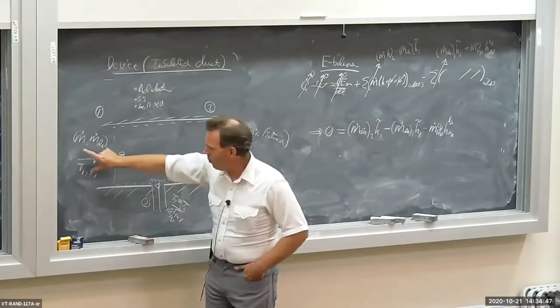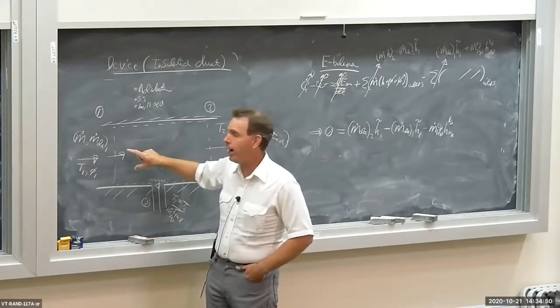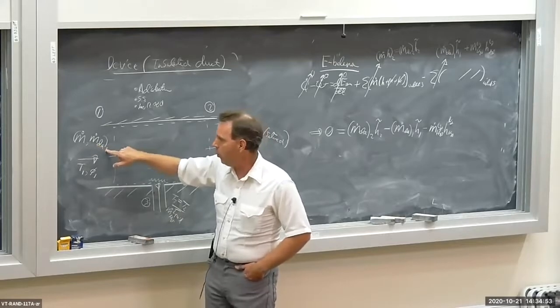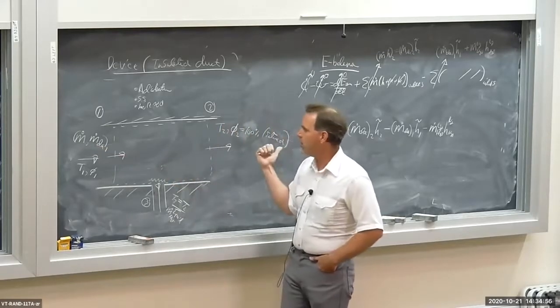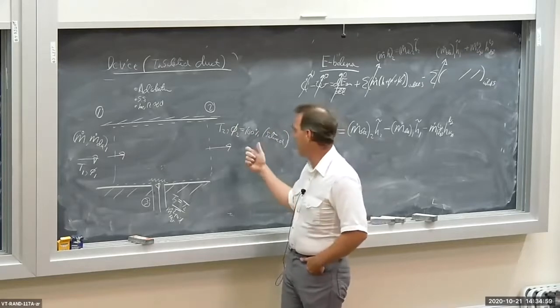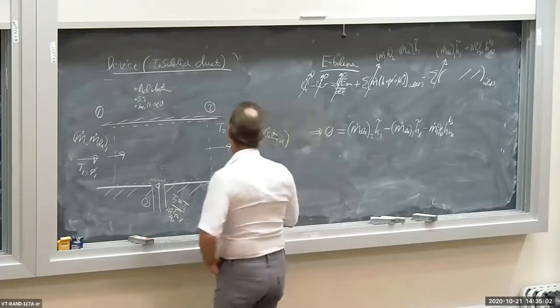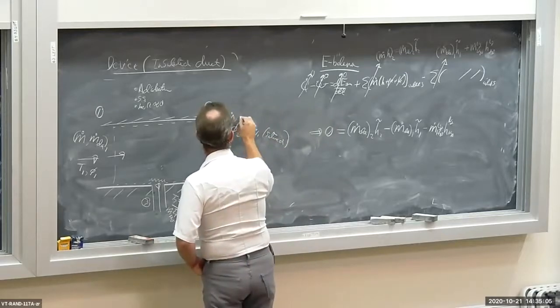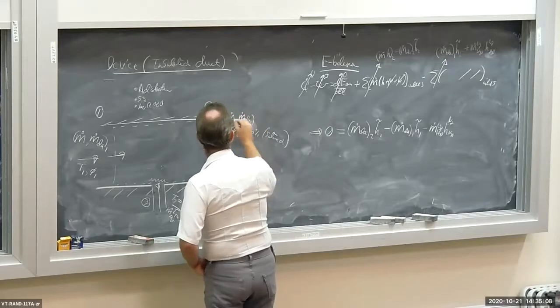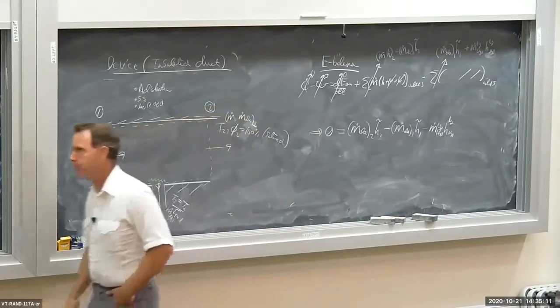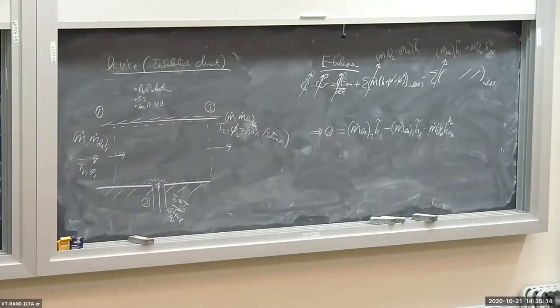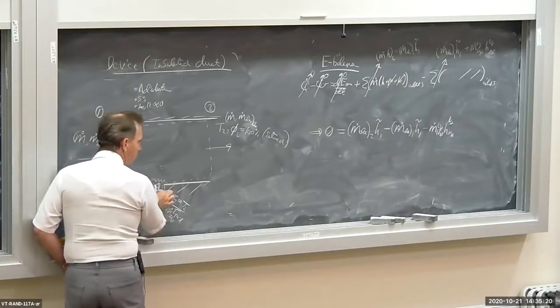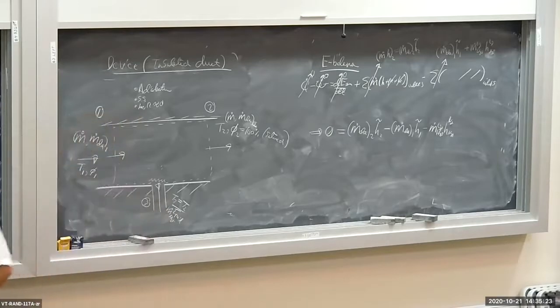So I have moist air flowing in on the left, some of which is dry air. So I have m dot dry air 1, and I have moist air leaving on the right, some of which is dry air. So there is an m dot dry air on the right flowing out at location 2, okay? So I have one inlet and one outlet for the dry air. By the way, no dry air comes through port number 3. It's only H2O on port number 3.